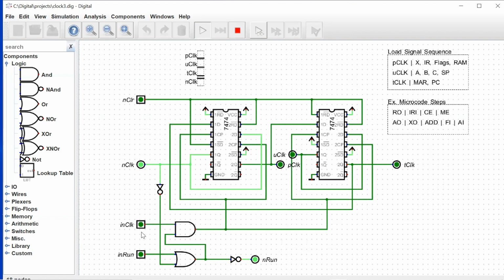We have a clock signal in, and this is just a component. It'll be included in a larger design, and that design will have the real clock signal that feeds the clock circuit. So that's what that is here. The other is the clear signal, to clear the clock back to reset the clock, and that's negative active. Okay, so let's set this up to run. We want to put this in run mode, and we want the clear signal inactive so that